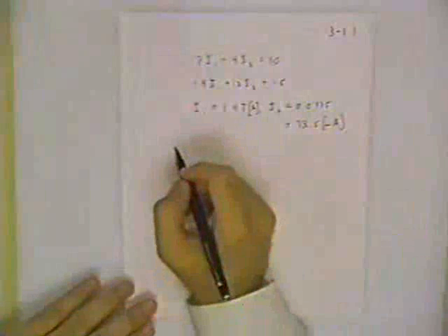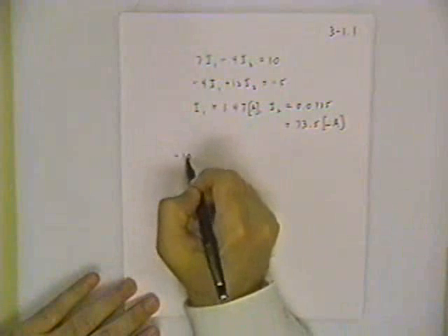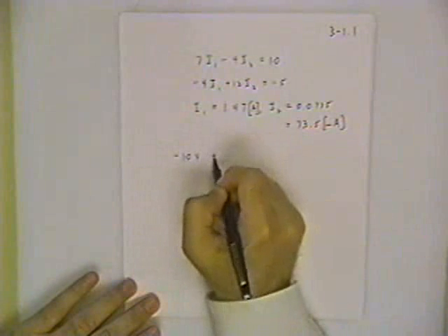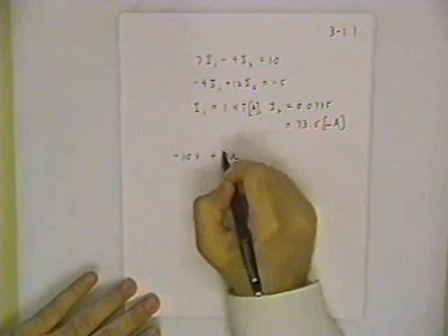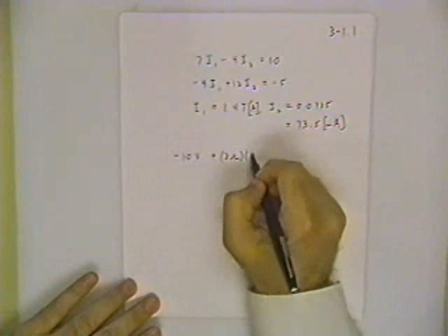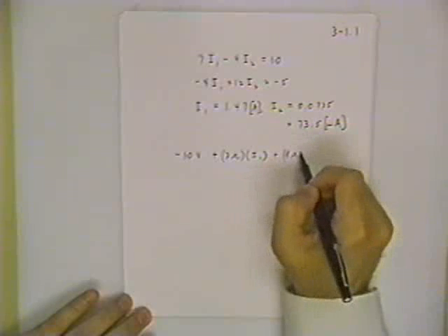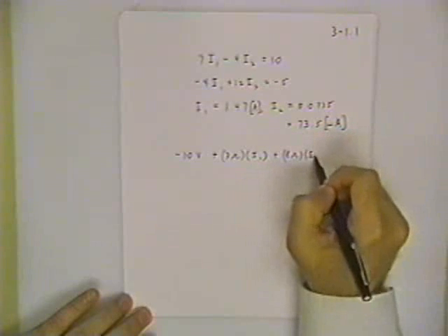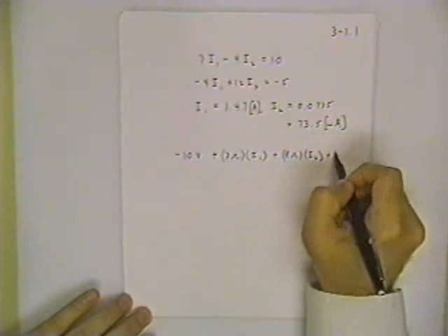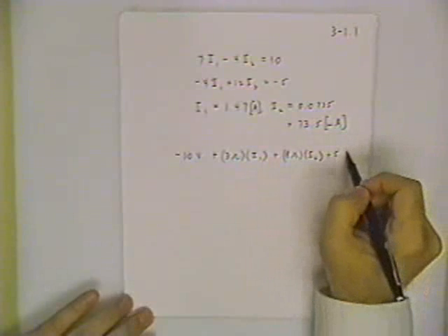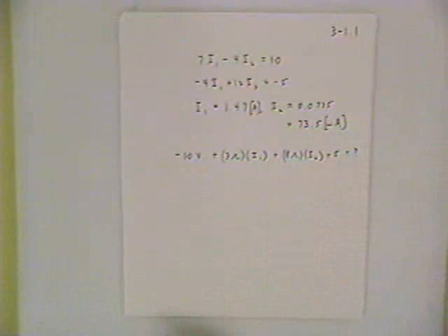Now, the check that I wanted to suggest to you is to use a Kirchhoff voltage law all around the outside loop. So if you refer back to the circuit diagram, I'm going to write down the KVL for the outside loop, and this is what it would look like. If you have the 10-volt source, and then you have the 3-ohm resistor, the only current going through that 3-ohm resistor is the current I1. And then we have the 8-ohm resistor, and the only current going through that is I2. Then we have a 5-volt source, and the question is, what does that total out to be?